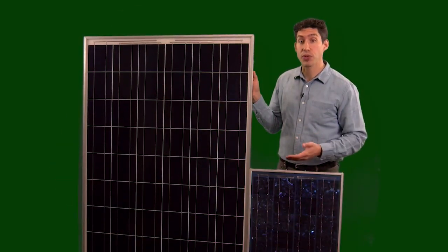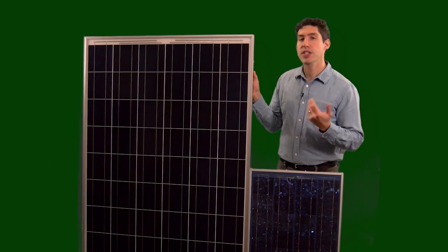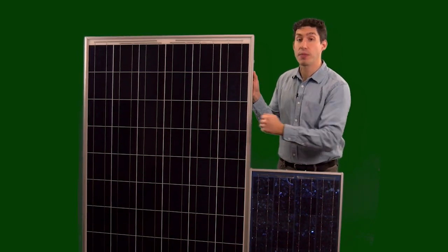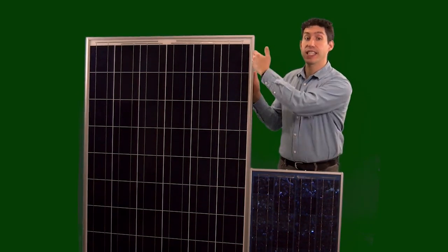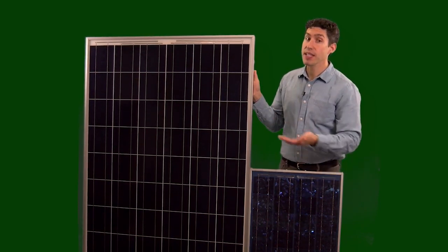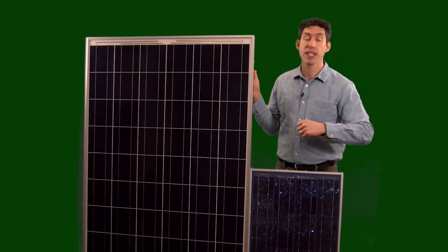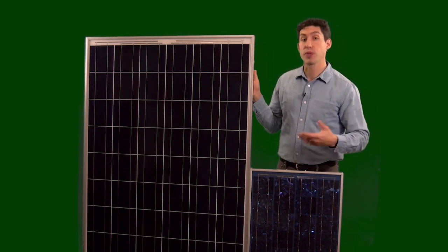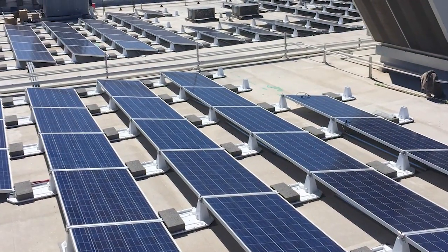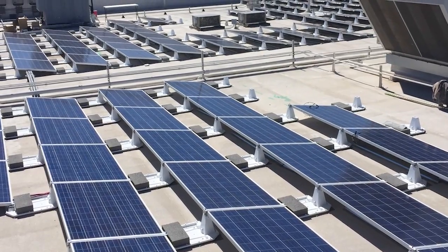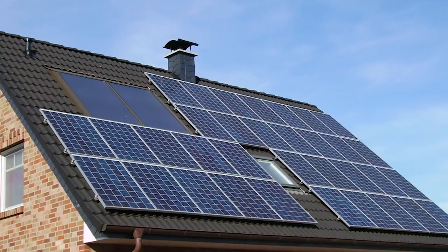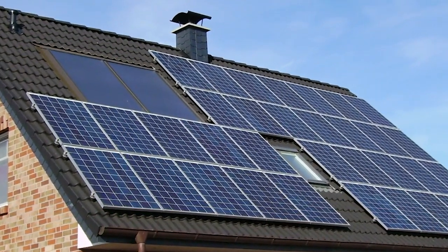Recently, larger modules have become much more attractive since there's a larger ratio of active area, or PV area, relative to the inactive frame area. There are limits on size, however, due to manufacturing limits, losses due to series connections, and weights that are reasonable for rooftop installers. There are some spacing limits when modules are tilted on rooftops or a ground-top system in order to prevent shading from one module to the other. Building code also has limits on module coverage from the bottom and sides of a rooftop.